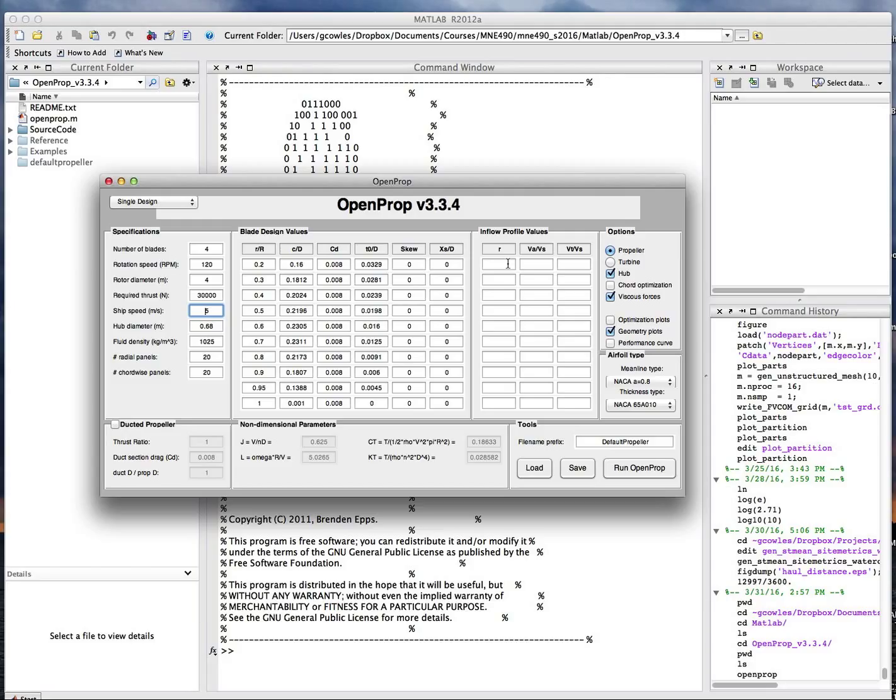We're going to assume a uniform profile, uniformly slowed down by the wake factor to be slower than the ship speed. So where it says ship speed here, I'll say in the homework, use advance velocity. Leave this blank. If you leave this blank, it assumes the wake is 0 and that there's no azimuthal, or circumferential, I should say, velocity field either. So it'll basically fill these values in with very simple values.